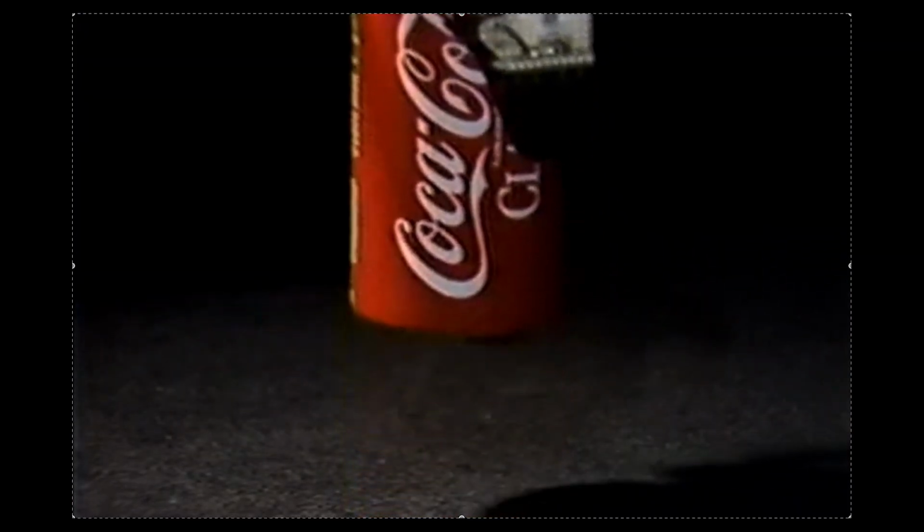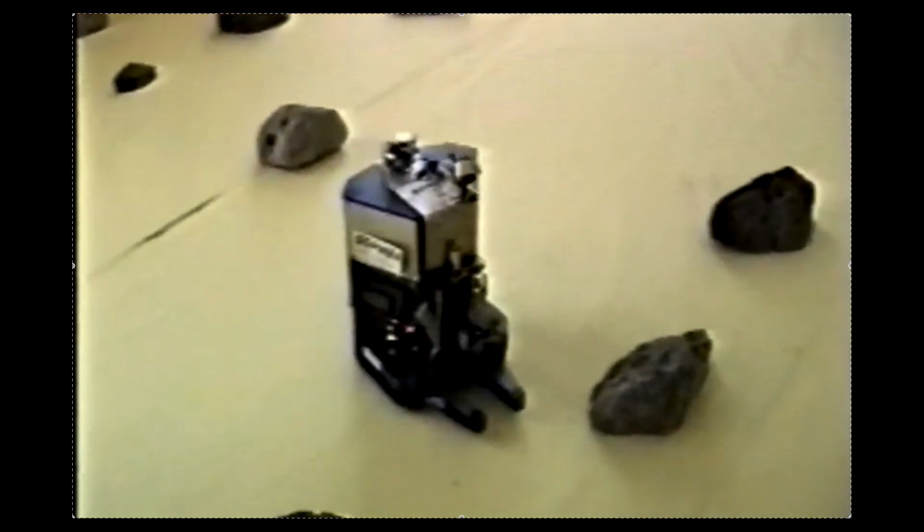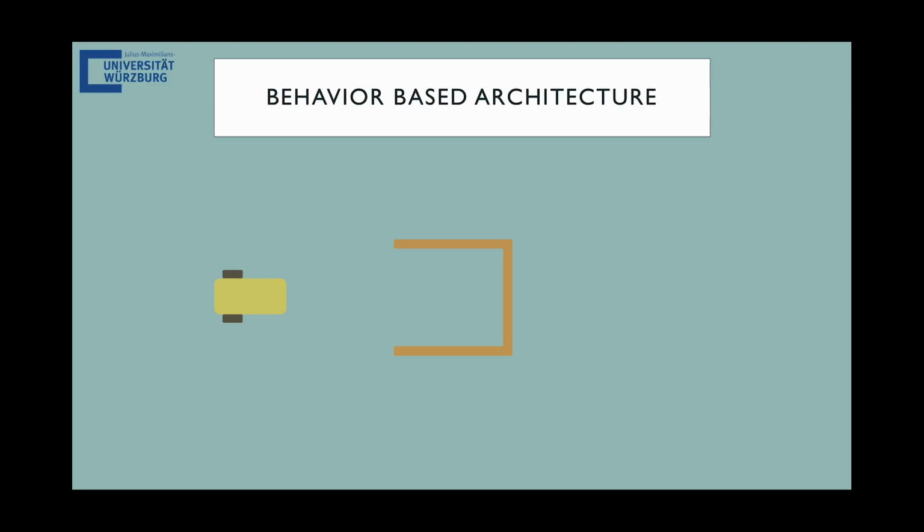This is because the individual programs are often dependent on other programs, which can lead to conflicts and infinite loops. This becomes clearer when we take a look at our robot with the two programs, and always rotate by 120 degrees after stopping. Assuming the robot drives into a three-sided box, it will get stuck in this box forever and turn in circles.